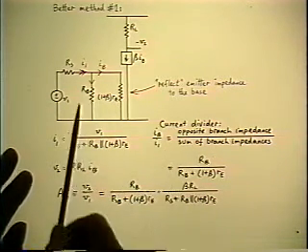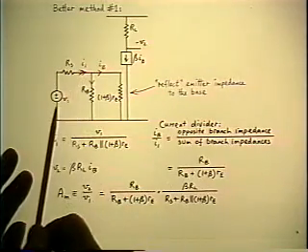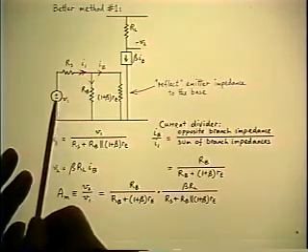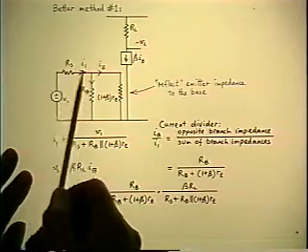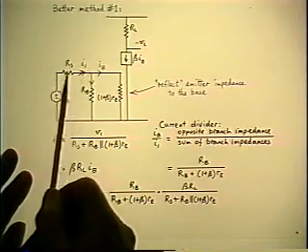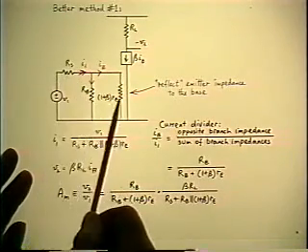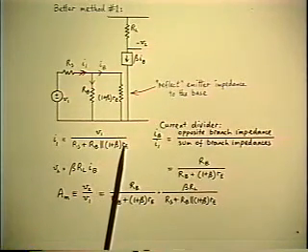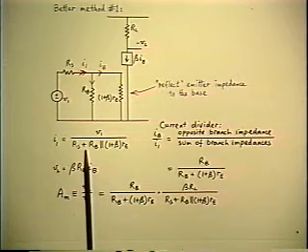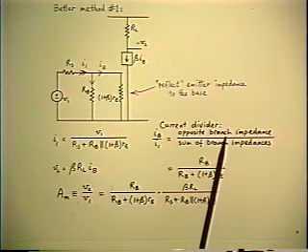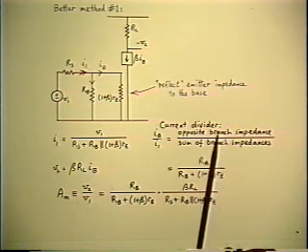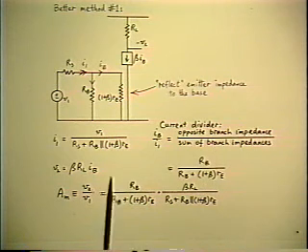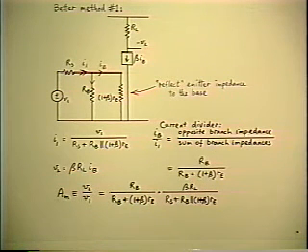Okay, having got that, we now want to know what I1 is as a function of V1. So that's V1 divided by the total impedance seen by V1, which is RS plus RB in parallel with 1 plus beta RE. Now, don't multiply that out. That's simply raising entropy unnecessarily. It's already in low entropy form. Leave it that way. Don't waste that information.